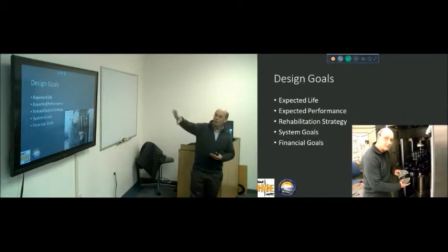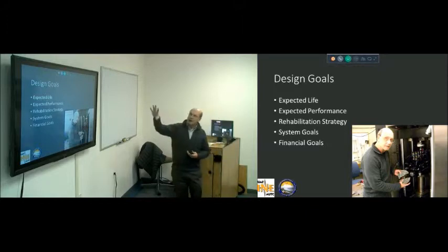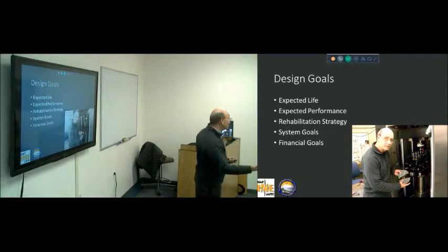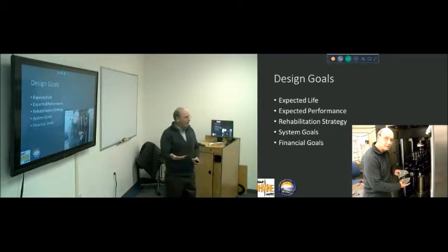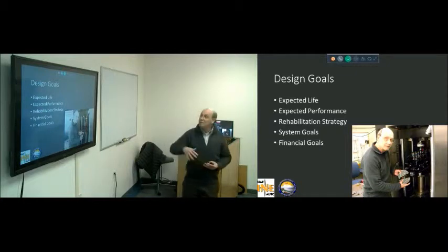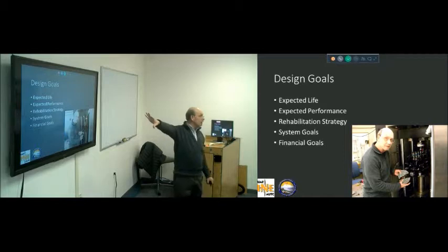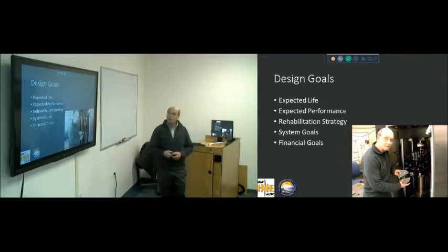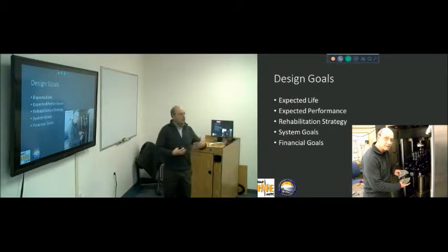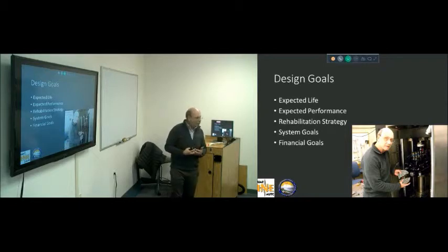Design goals, we've kind of gone over some of these. But expected life, performance, rehabilitation strategy. What do you plan to do when it wears out? Are you going to overlay it? Are you going to mill and fill? Are you going to do full depth reclamation? You need to be thinking about those things as you design the pavement for today. How are you going to rehabilitate or reconstruct that thing? What are you going to do in the future? Because what you do today is going to impact those decisions as you move down the road. So think about them today.